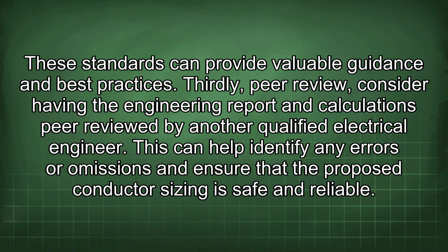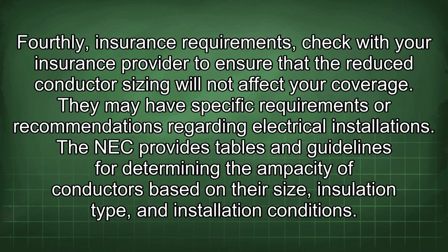Thirdly, peer review. Consider having the engineering report and calculations peer-reviewed by another qualified electrical engineer. This can help identify any errors or omissions and ensure that the proposed conductor sizing is safe and reliable. Fourthly, insurance requirements. Check with your insurance provider to ensure that the reduced conductor sizing will not affect your coverage. They may have specific requirements or recommendations regarding electrical installations.